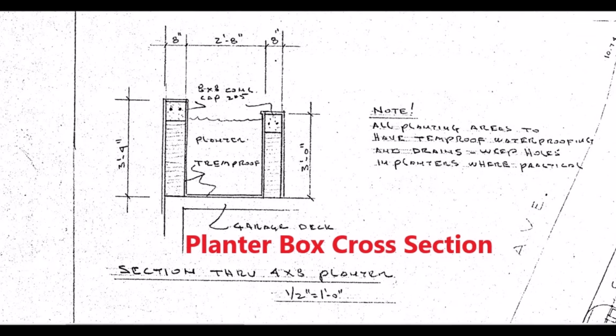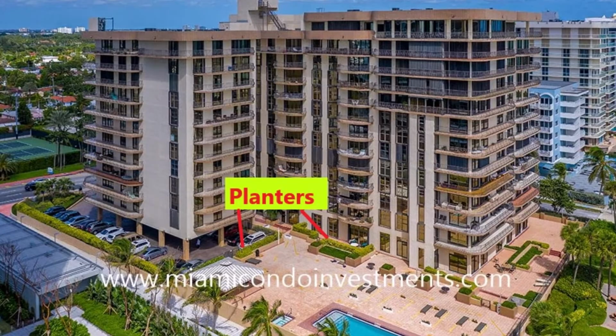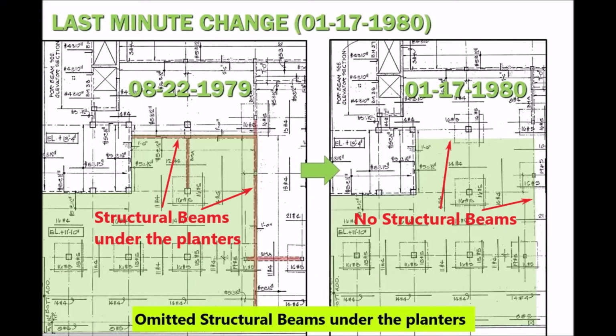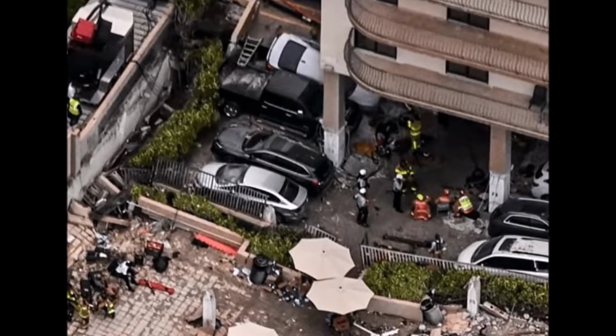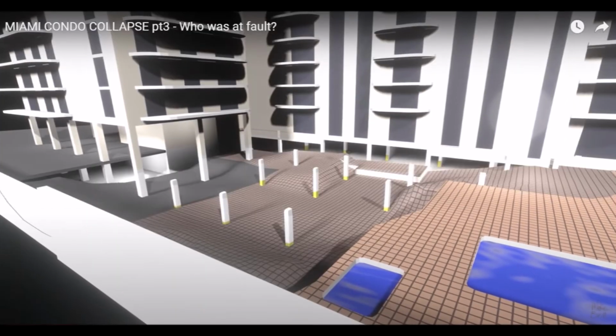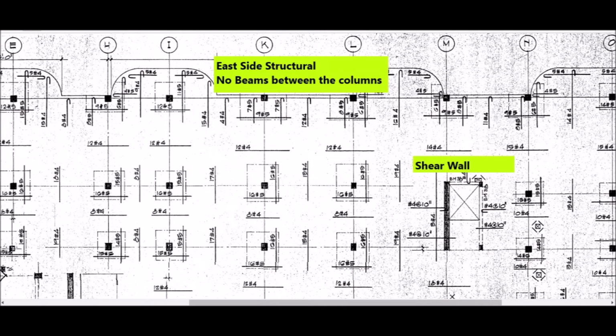And here looking at the cross section. In his calculations for the pool deck area, he determined that the factor of safety was 1, meaning they designed it for the exact weight that it would hold and leaving no room for error in either the design or during the construction of the building. You see here where the planter boxes fell and precipitated the collapse. It's because the pool deck slab connects to the east side of the building. If you look at the structural drawings, you'll see a small shear wall at the stairwell only on the east side of the building.